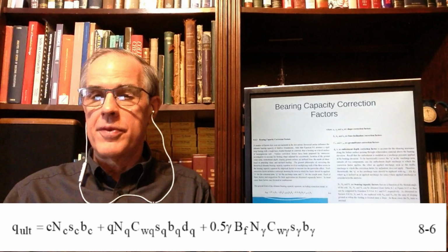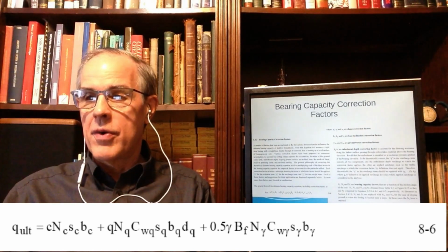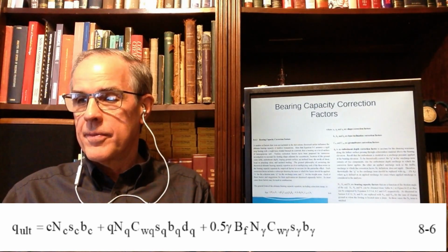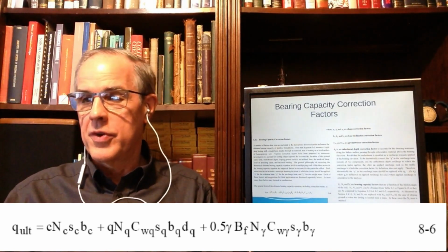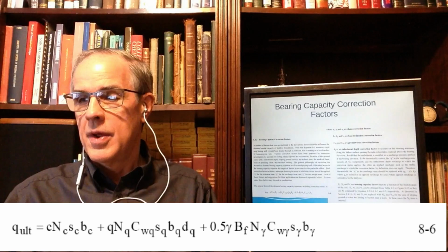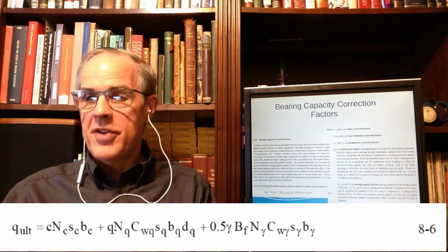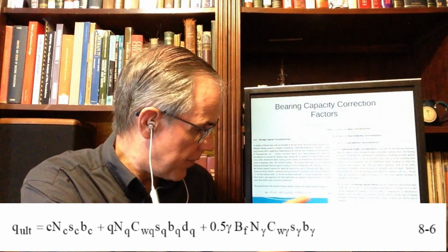You've got the shape correction factors. We have the groundwater correction factors, the embedment depth correction factors, and the base correction factors. Those correction factors are the ones we're going to discuss, and they're basically additions, and you see the formula here gives a lot of those.